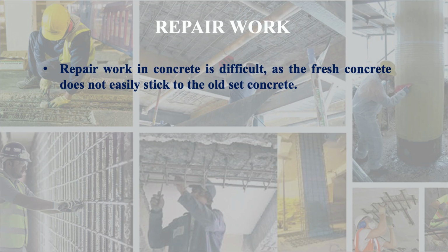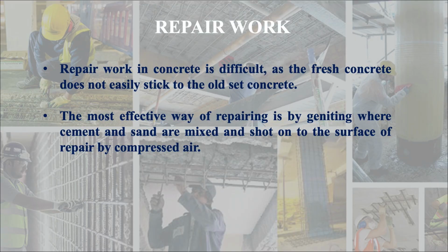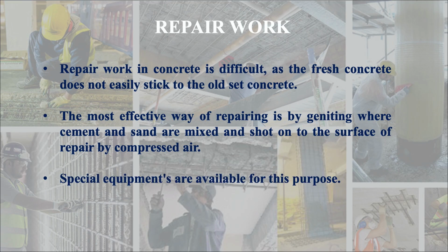Now, what repair work can we do? Repair work in concrete is difficult as the fresh concrete does not easily stick to the old set concrete. Means it is very difficult to make a bond between the old concrete surface and the new concrete work. The most effective way of repairing is by guniting, where cement and sand are mixed and shot onto the surface of repair by compressed air. Special equipment is available for this purpose.